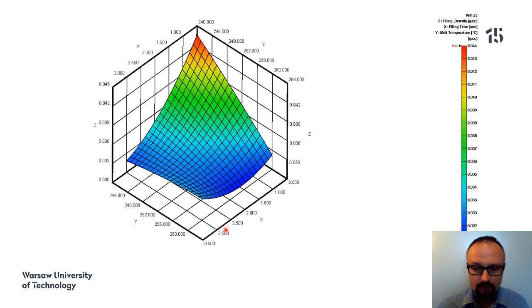We cannot inject too slow, because we'll reach a slight increase in our filling imbalance, because we're also increasing the shear rate, as the cooling effects of the flowing polymer take advantage, and the wall of our runner starts to freeze.